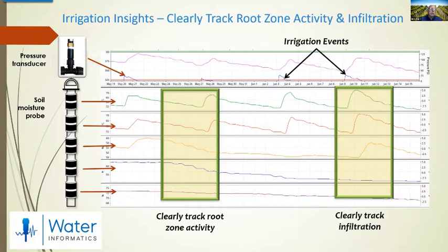Super important, because at the end of the day, you'll want 15 to 20 pounds. And if that transducer doesn't pressure up completely, or it doesn't show the pressure, you've got a break in the line, something's going on, the pump's not pumping enough. So those are really important things. So we like the idea that we can actually set an alert on that transducer that says, hey, you're in low pressure, you probably ought to go out to the field and have a look.